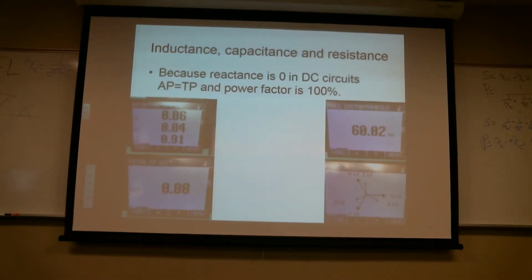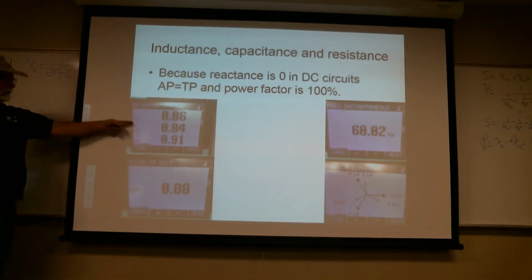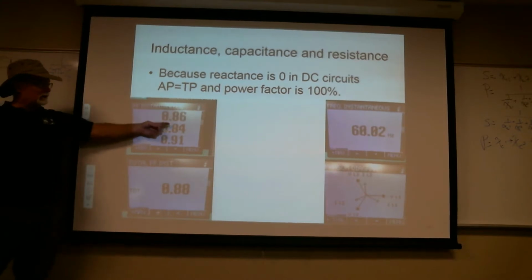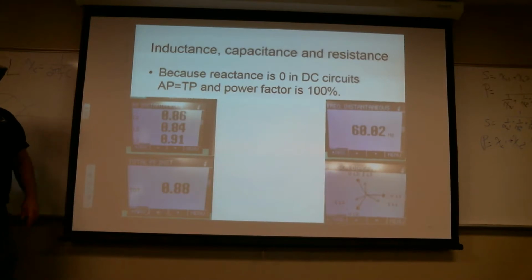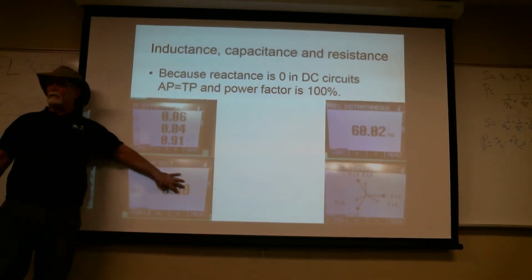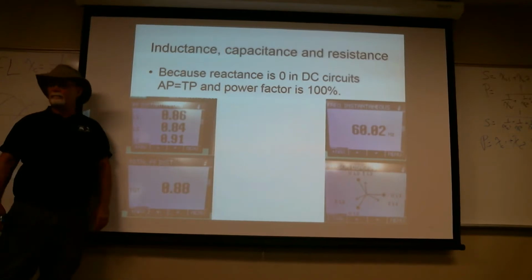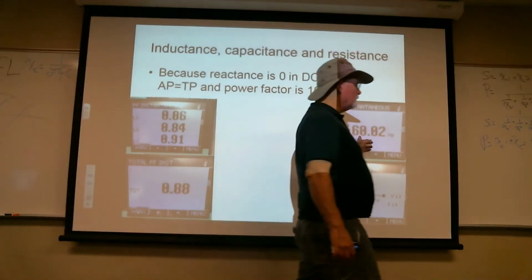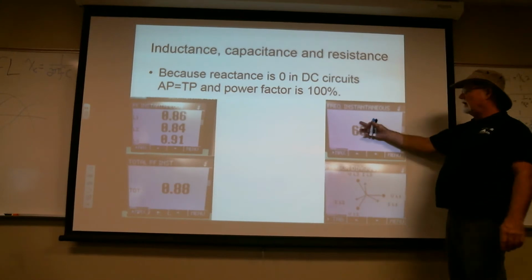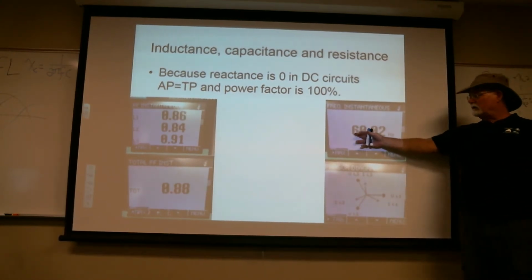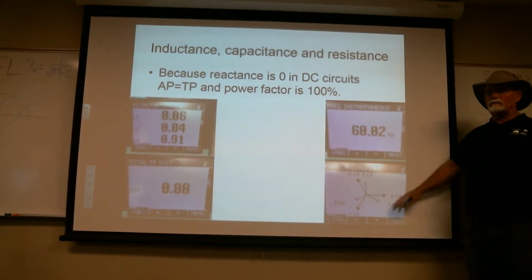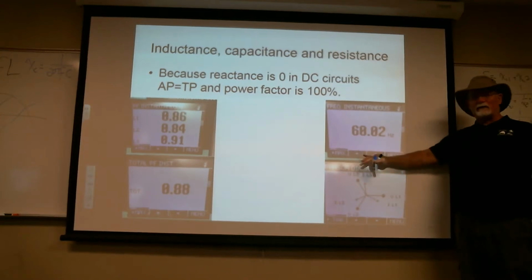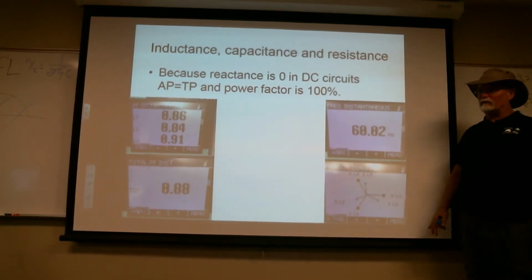Yeah, so here's an example of a picture I took some time ago. This actually shows the three individual phases and the power factor for each individual phase, and then the summative average of all of them. So in this particular case, we were losing 12%. All right? This shows the frequency, and that's that little panel up there, and they keep it pretty tightly controlled. It usually reads 59.99 or 0.01, sometimes it gets up to 0.2. But as soon as this starts changing wildly, phase and amplitude start changing wildly.